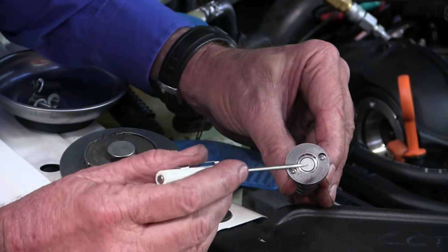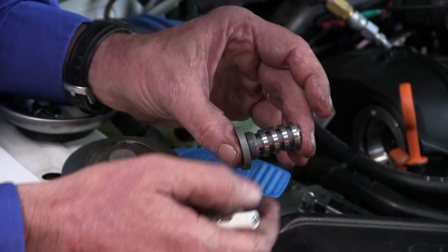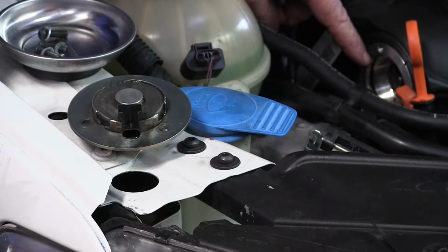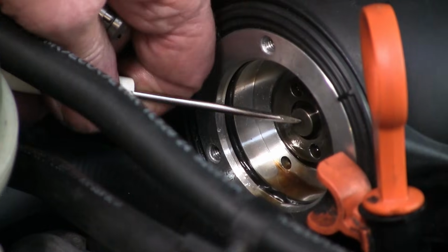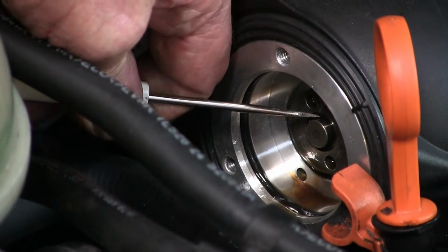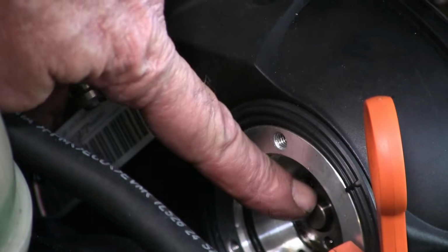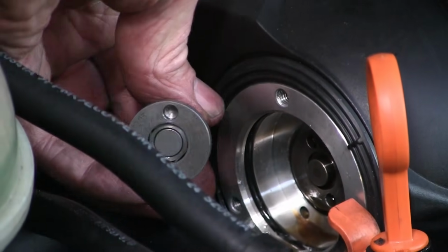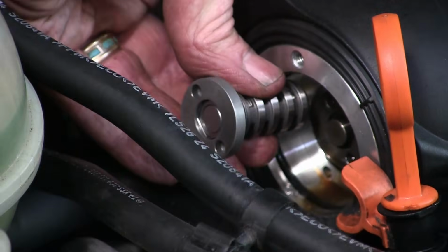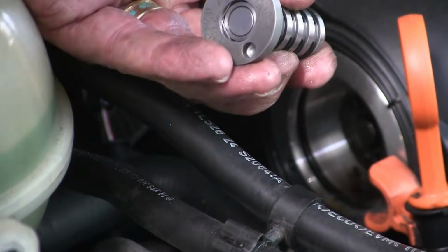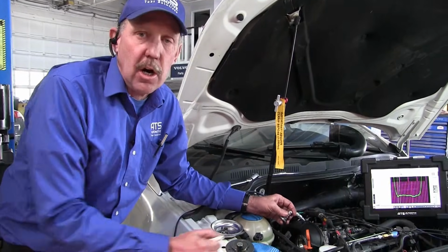Now what happens is this valve breaks, and when it comes out, I have full oil flow going to the phaser, and it holds it out. If we look at this right here, we can see that this one in this engine is broken. Do you see how this piston is sticking out? Do you see how high it's sticking out? Now look at the difference. Do you see how this one is in and this one is sticking out? This is broken. What needs to happen now is this solenoid, this valve assembly, needs to be replaced. So we'll pull this one out and get that one in, and then this vehicle will be ready to return to the customer. It'll fix the car's problem.